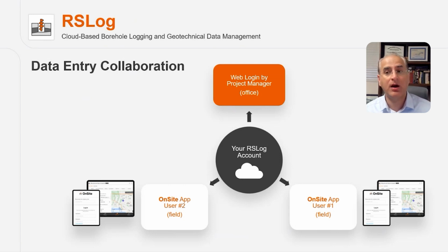And this way you can see how the site investigation is going. They can share their data before terminating a borehole, which is in a lot of cases very important. If you have a piling project, you don't want to end the borehole in soft clay, for example, right? You may want to go another 10 feet or 15 feet. So all of these could be done by easily sharing the latest data with you.